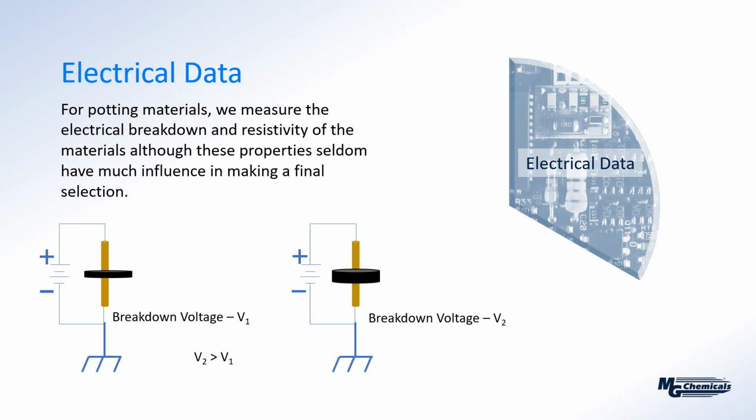One thing you have to notice is that the sample thickness will have an influence. So what we do in that situation is we try to standardize it to a given thickness, and I think we do it to about 3/8 of an inch or something.